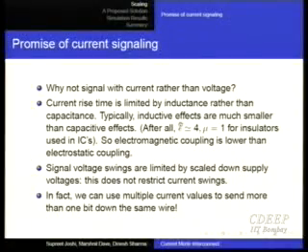But if you look at the physics of it, actually the results are somewhat pessimistic, because it turns out that what capacitance does to voltage, inductance does to current. Actually it is the quantitative advantage that current mode has, because it turns out that the inductive effects are much smaller than capacitive effects in general. Part of it is this, that when you come right down to the physics of it, the average dielectric constant is like that of the oxide, which is about 4, whereas the average mu is like 1. None of these materials is magnetic. So in short, the magnetic effects are much smaller than capacitive effects.